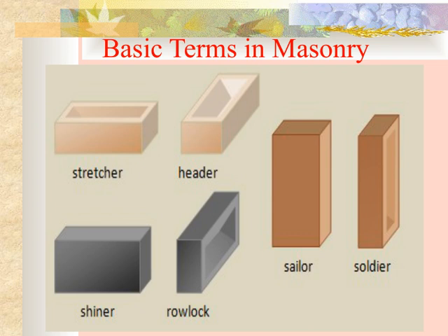When we talk about masonry, we're referring to the craft of building with individual units, like bricks, stones, or blocks, and the mortar that holds them together. Knowing these terms helps us appreciate the skill and precision involved. For example, terms like course, which refers to a single row of masonry units, and bond, which describes how these units are arranged for strength and stability. These basics connect directly to the overall theme of craftsmanship and the importance of strong, well-designed structures. By understanding these foundational terms, we gain a deeper insight into the art and science of masonry.